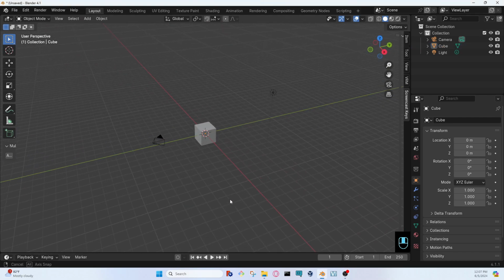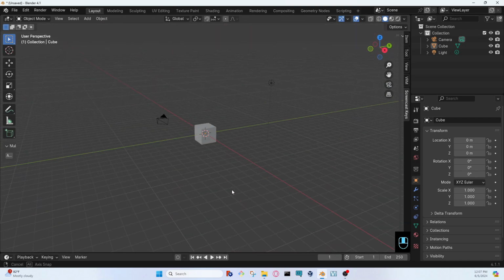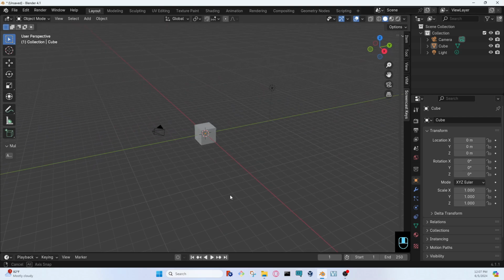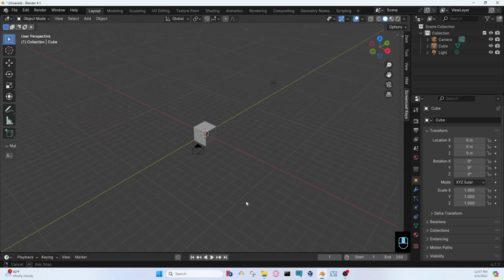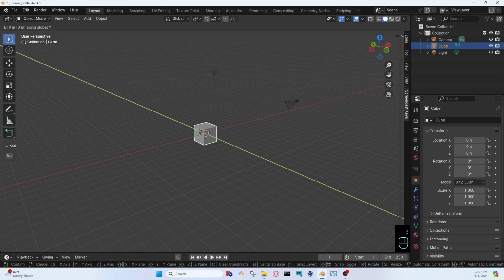After you've moved things around, and you want to move things specifically on an actual axis and not by freehand, like say you want to send this default cube down the x-axis and you don't want to move him from the z or the y, you can again grab him. After selecting him, you can grab, and then select the axis by hitting X, Y, or Z relative to the axis, and then you can move your cursor and he will be snapped to that axis.